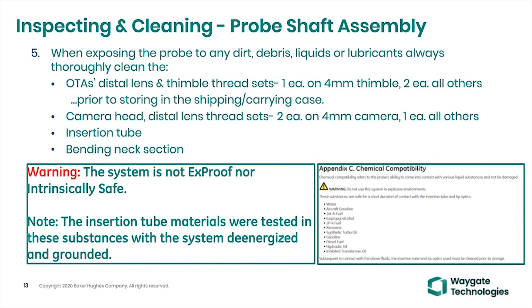And then you want to clean all of the threads around the camera, and you want to clean all of the threads inside the tip adapters. And when you're doing that, folks, please do it under some kind of magnification so you're not, A, bending or damaging the pogo pins on phase tip optics, or B, you're not digging out and removing the O-rings that are inside of that proximal body of the OTAs. So just some thoughts around that.